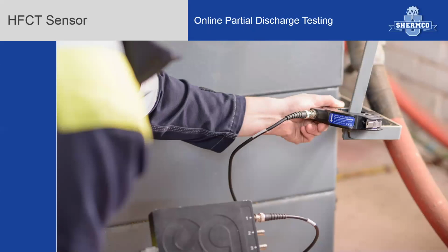HFCT sensors have a distinct advantage of being able to detect partial discharge signals on cables from long distances up to several hundred yards or several kilometers. Now, the only limitation is going to be the type of shield and how good that shield acts as a conductor as to what is the actual range and how far away you will be able to pick up PD transients. Now, this means multiple PD signals and noise can be potentially picked up and detected on these CTs.